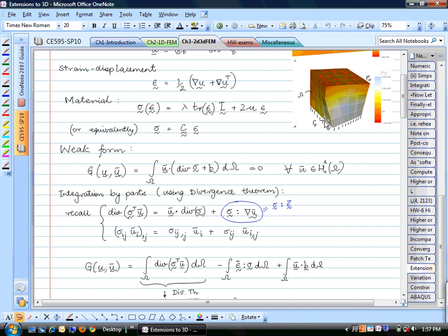What that means is, in 2 dimensions we were able to plot the shape function for our triangular domain. You can plot the tent type shape functions and visualize them in 3 dimensions for 2-dimension problems. But when you come to 3 dimensions, it is not possible to plot the shape function. The only way you can do that is using these types of colors. But the ideas remain pretty much the same. You have to make sure that your element is continuous and smooth within the element, and it is compatible across the element boundaries. So those are the types of conditions that you have.